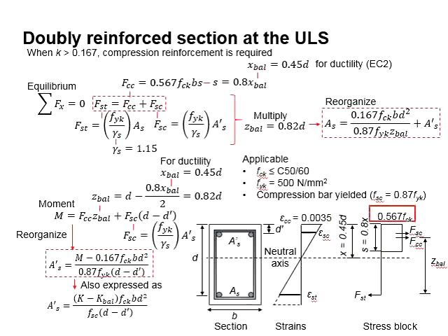The maximum compressive stress of the concrete is determined by the design strength of the concrete. The lever arm will be determined by the distance between the compressive concrete and the tension steel. As there is a compressive reinforcement bar, the lever arm will be equal to 0.82d.